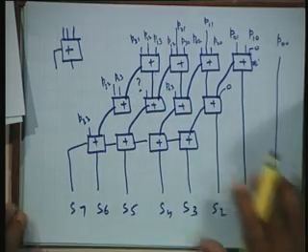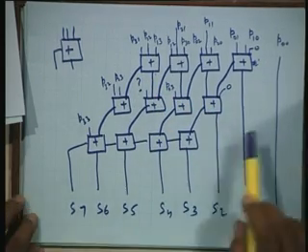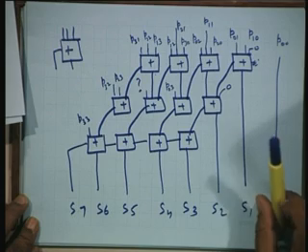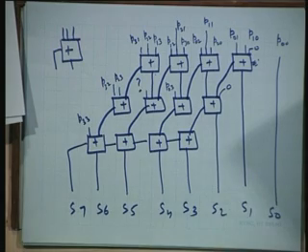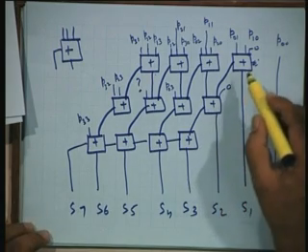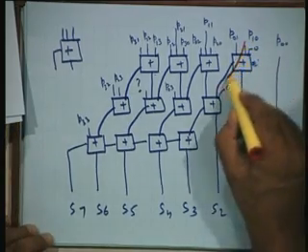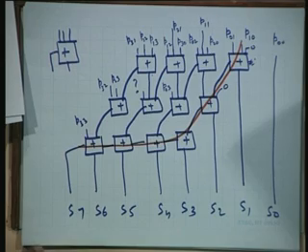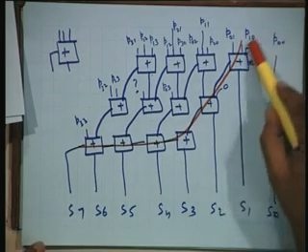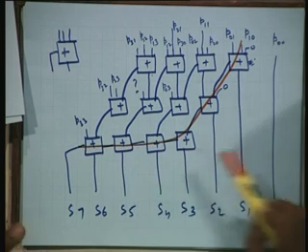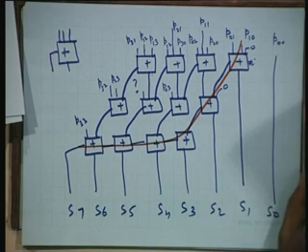So you can check. But anyway, this is the overall structure of this multiplier, and you would notice that the delay now is dictated by this path. So you have one diagonal movement and one horizontal movement. So roughly it will be proportional to 2n instead of 3n.